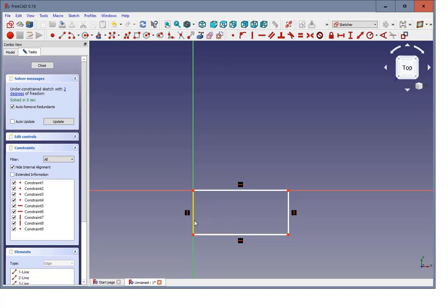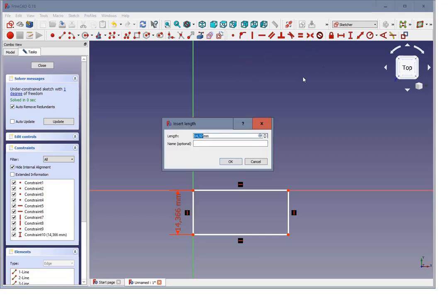The next step is I need the width, or the depth of this frame, and that one is going to be, let me look at my recording, 20 millimeters, and I call it frame depth.